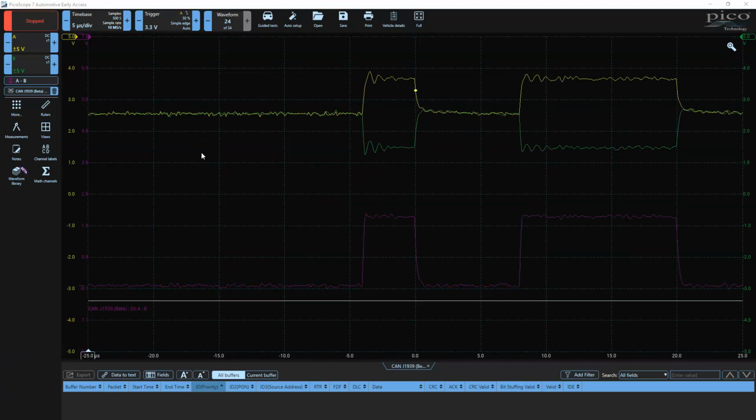One other thing I probably need to add, I've mentioned that these 120 ohm resistors, just plain resistors, are what we would call passive termination. And by passive, it means that there are no electronic components within it. It only contains resistors, capacitors, and inductors. So that would be a passive device. Something that is an active device would have voltage regulation, would have other electronic components within it. So there is something that is also referred to as a terminating bias circuit, or a TBC. These are perhaps called an active terminator by some manufacturers.